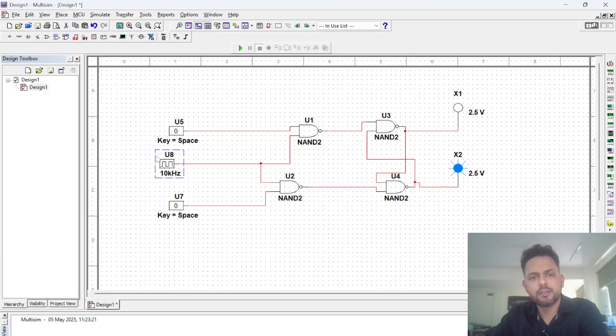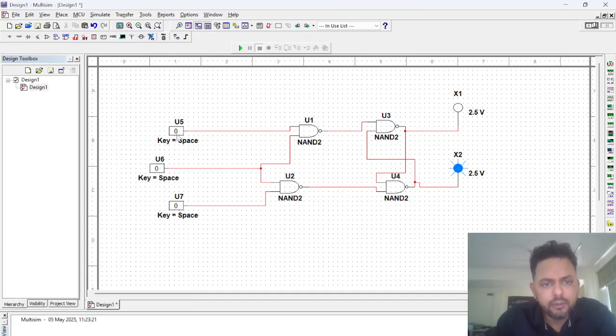Just stop this simulation, remove this clock now, and copy this again. Just copy here. Okay, now connect this to both the pulses. Okay, now give it a 0. Okay, this is the initial state you're getting. So if it is 0 0, the initial state is not changing, it always remains the same. This is memory. And as soon as it becomes 1 and it becomes 0, both become 0, you again get memory, no changes here.